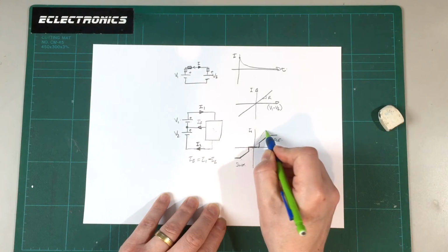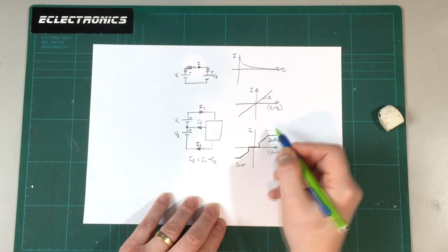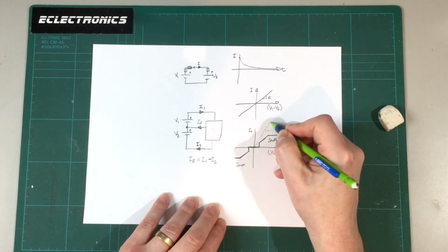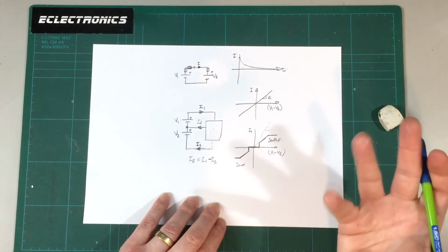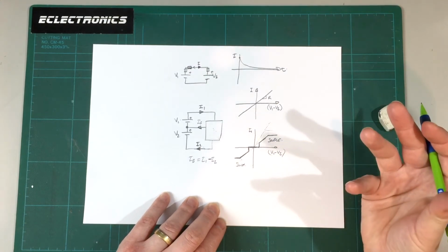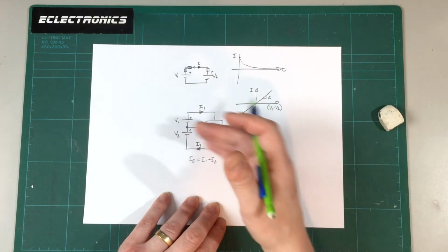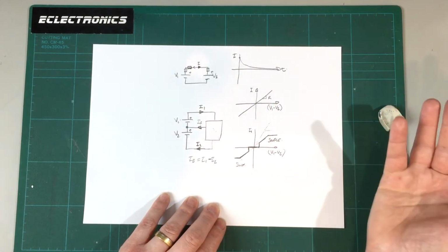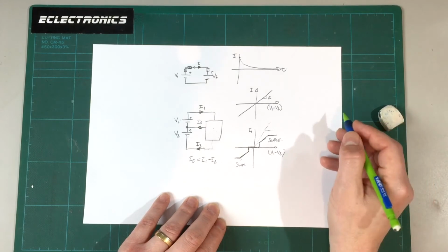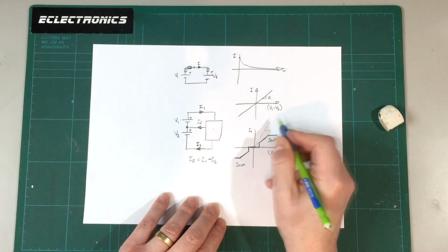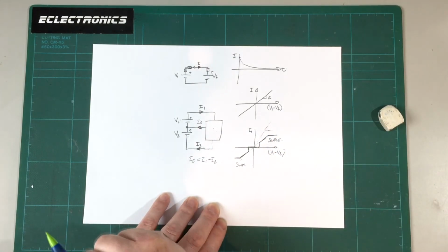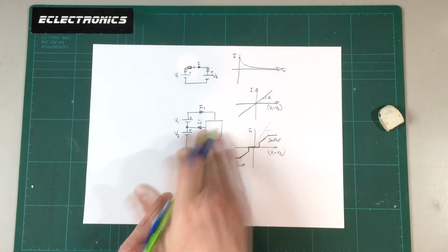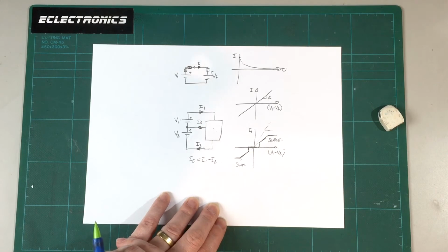Again, we may see that they have a current limit on the capacitive ones, but some of the literature I've read suggests that they don't. It may just keep on going. So presumably there's some point at which you can break these capacitive charge balancers. If the voltage differential on your cells is too great, or one of the cells gets short-circuited, maybe, the current could become very high in theory. So again, it'd be interesting to see what the characteristic for the capacitive type balancers is, and compared to the inductive ones, which we know have a current limit because of the semiconductors used in the chip.